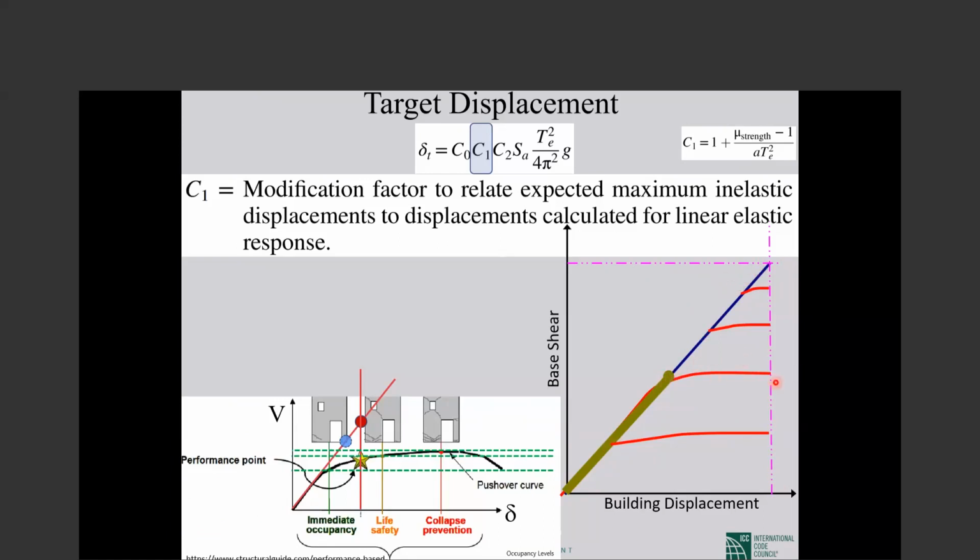Is there any relationship between the maximum displacement of a system when it yields and when it does not yield? Is it linear? It was found long ago that statistically, not for one earthquake but in average, for many, the maximum displacement is the same. Very interesting, very beautiful, so nice.